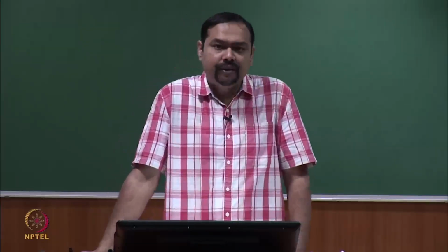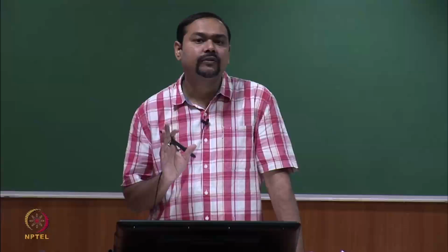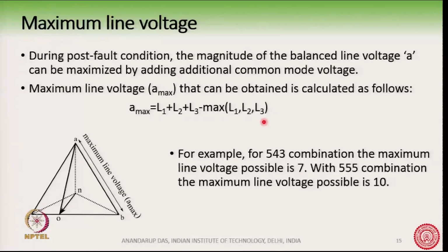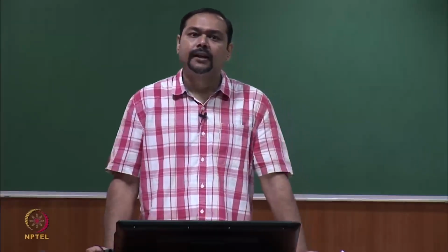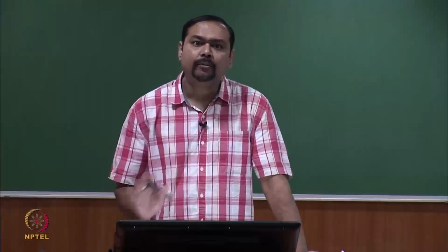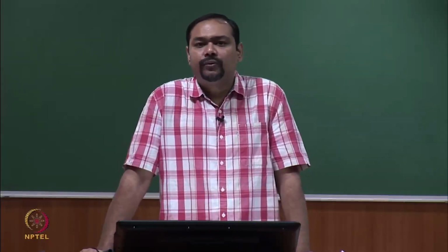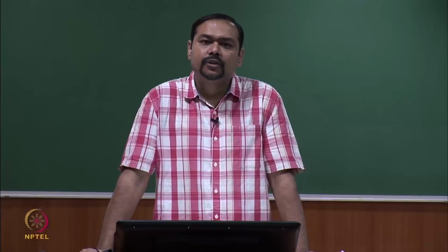As I was telling, this point O is something which is kind of like a degree of freedom. The point O is not fixed, it can move. There are many applications of this movement of the point O. Typically, a lot of research work goes on here. So far we have talked about the motor drive application, but suppose this cascaded H-bridge converter is used for feeding power into the grid from PV cells.